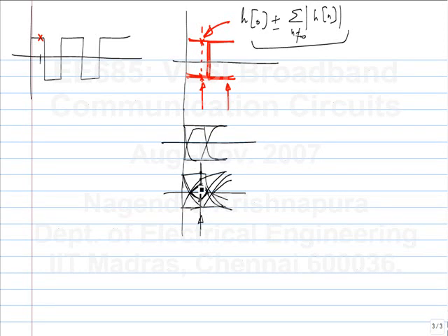So the vertical eye opening gives you a measure of bit error rate. If you add a given amount of noise, the vertical eye opening gives you the signal strength. Normally in a case like this, when you don't have any ISI, the transmitted strength is the signal strength. But if you have ISI, you may be transmitting a large signal, but the ISI can also be large. So it is the net that counts.